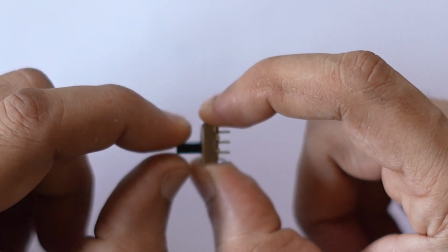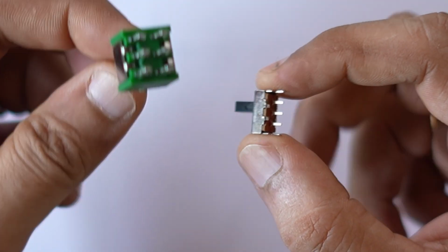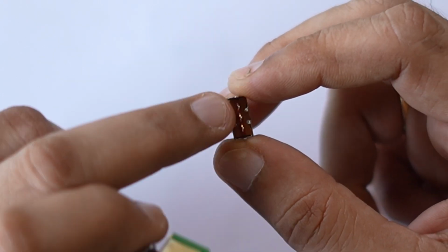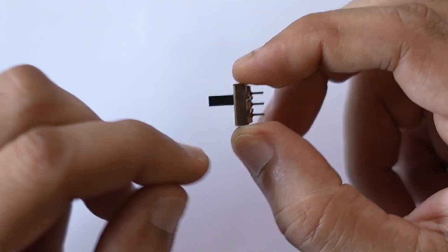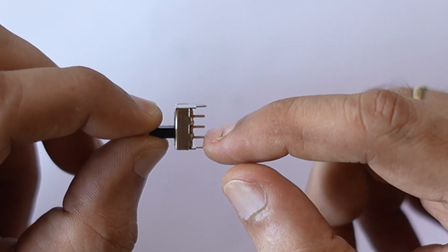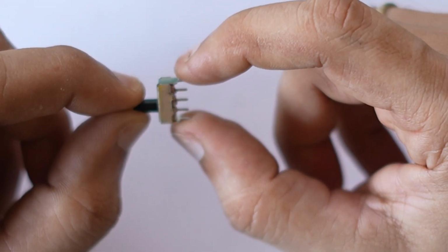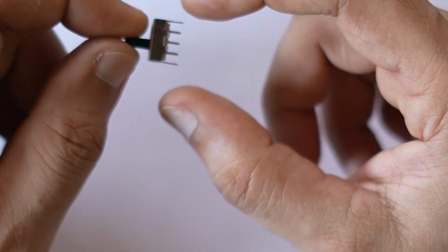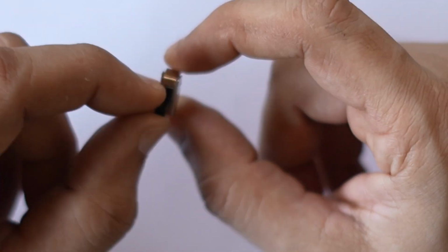This one has just two positions again, and functionally it's similar to the toggle switch, except you can see that since it has 3 pins, it is a single pole, but it has 2 throws, so on one side and on the other side as well. It just shorts the center and the bottom pin or the center and the top pin. And it also has additional pins which are connected to the metal body, because when you insert it on a circuit board, it provides the mechanical strength so that it doesn't break and fall off.